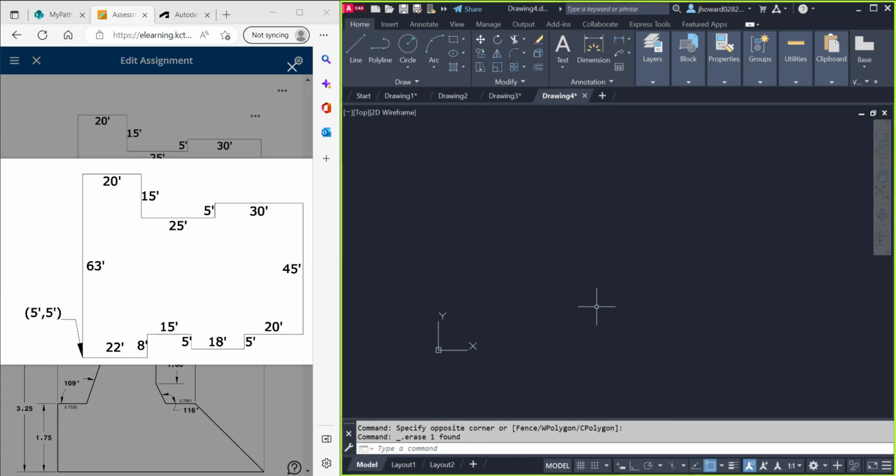The next thing that I want to show you on here is the direct line method. And you guys are going to love this. This is going to be so much easier than the absolute and incremental line methods. All you have to do is come down here in your status bar, and of course here is your object snap. It's turned on to a little bit of light blue there. But you see this little, looks like a little 90 degree angle there. You click on that, and what happens is it makes your line either go horizontal or vertical. Y'all see that? East, north, west, south. It won't let it go at an angle. If I turn it off, I go back into my angles. Y'all see that? So if I turn that on, it's really cool.